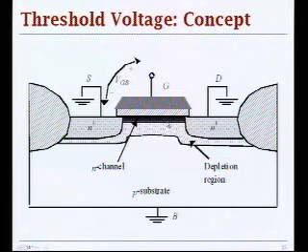And for very small values of this gate to source voltage, you have positive carriers attracted at top of your gate oxide on the gate terminal, and then you have negative charge underneath your gate in the channel region. First, this negative charge is actually built by repelling holes from this region, and you have immobile acceptor ions sitting here.